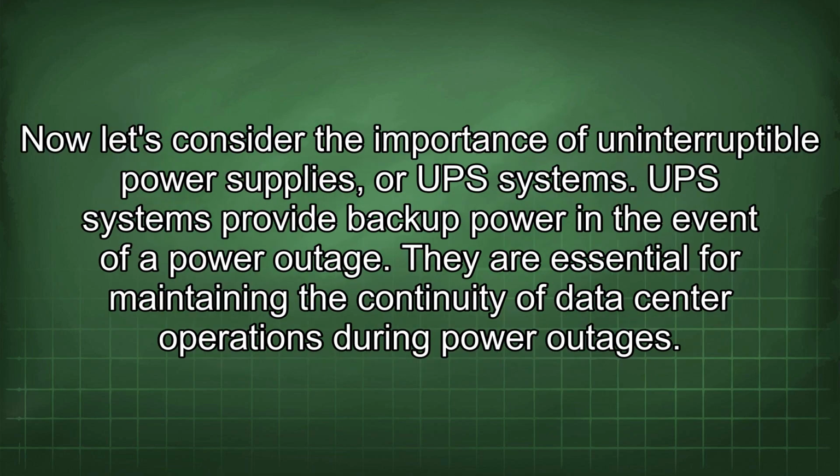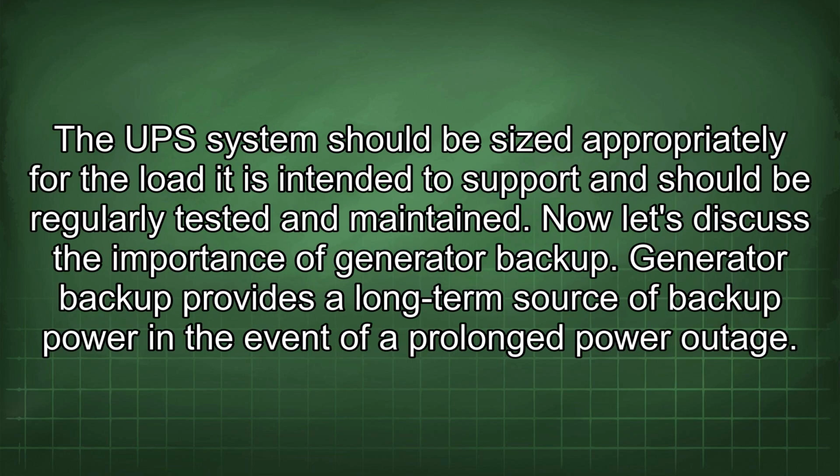Now let's consider the importance of uninterruptible power supplies, or UPS systems. UPS systems provide backup power in the event of a power outage. They are essential for maintaining the continuity of data center operations during power outages. The UPS system should be sized appropriately for the load it is intended to support and should be regularly tested and maintained.